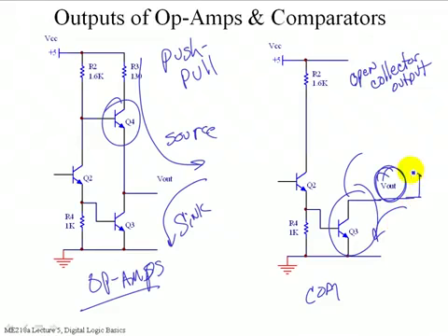Yes, a pull-up. If we add an external resistor to the output, then this external resistor can cause the output to go up. And that adds a level of flexibility because the plus that I use on the other side of the resistor doesn't have to be the same plus as the power supply for the comparator. So I can take a comparator with 5-volt supplies, pull this up to, for example, 3.3 volts, and make an output that goes from 0 to 3.3 volts if I want to connect to a device that likes to see 3.3 as its input.